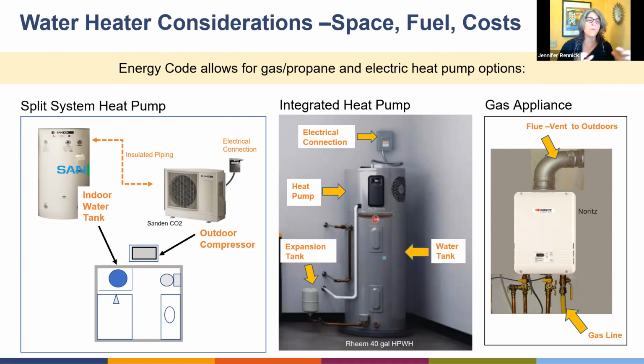So you could put the hot water tank inside the ADU, like in this example, inside the bathroom area, a very compact design. And then that compressor can go outdoors, and it can even be wall mounted. And it really simplifies the whole setup and saves space, and you don't have to run the gas line. And both of those are totally acceptable.